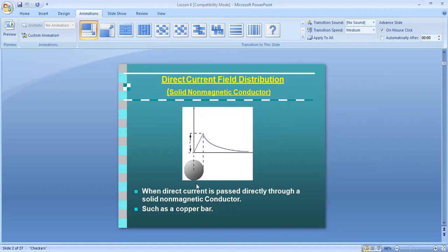So now here, this is the central conductor; we saw one conductor. What was the purpose of the conductor? Why are we using a conductor in magnetic particle testing in the central conductor technique? To pass the current. The magnetic lines of force are generated around the conductor, and we pass them through our jobs. Sometimes we do magnetic particle testing of gears or hollow components, and we use the central conductor technique. For hollow pipes also we use it. So in that case we use a conductor, and here we are going to study the conductor.